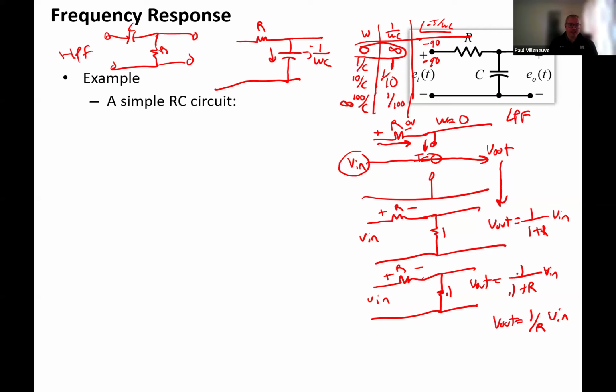An inductor is just a piece of metal wrapped in a ring. Usually you can just take a piece of iron, wrap some wire around it, and the number of turns will help you determine what the inductor size is going to be. So the reason why you can, but you don't see a lot of RL filters, is because you just don't have the availability of already built inductors as you do capacitors.